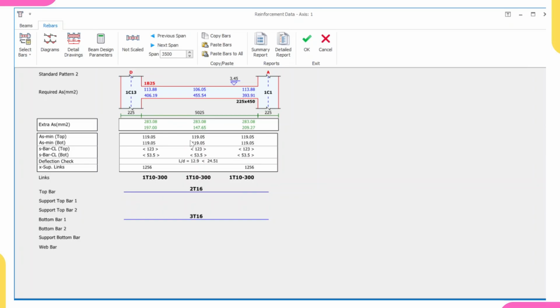Yes, and in this African country, they tamper with quality. All these production companies are trying to make profit from their product. So our Y16, that's our reinforcement Y16, it is no longer Y16. Because I'm based in Nigeria, if I go to the market, my Y16 will be something like Y14, Y15, or even Y13. None of them will be up to Y16.